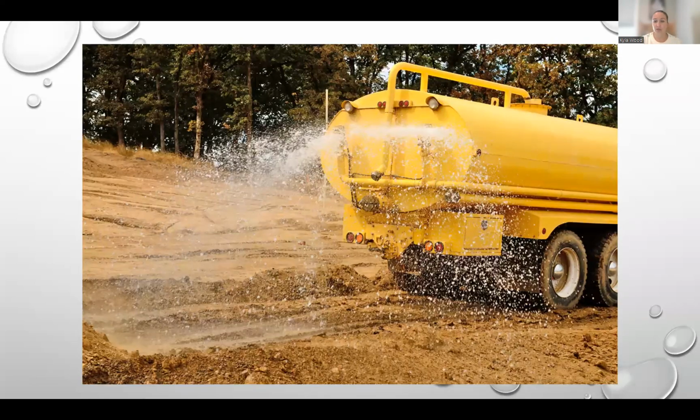Here we can see it in the water truck. So those are some easy application methods. You don't need to apply it separately. You can add both the granular PAM and the liquid emulsion as the last additive in a hydroseed or water truck mix. It is important to have a mixing unit in that truck to make sure it's fully mixed up. And then there is a limit on how much you would put in.